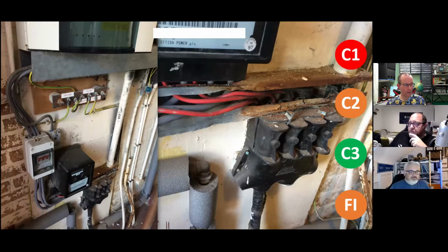27% agree with that, C2. But I'd also throw an FI in there as well. It's definitely a bit more work. I'd definitely be making a phone call to the DNO and say, look, hang on a minute, lads. Is this right? There's a lot of rust and corrosion here. You've got a possible fused neutral there. An FI would be my first choice. On the rusted trunking, C2 makes it C2, but on the DNO cutout, definitely an FI. Okey-dokey. And yes, they are single insulated tails.